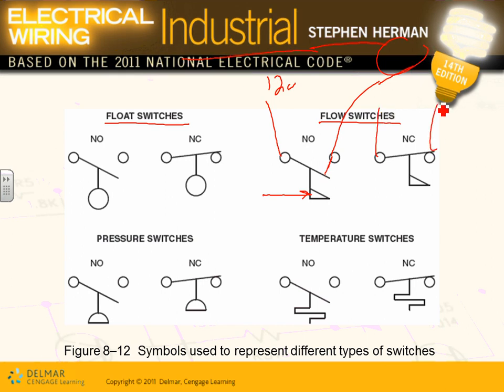So you bring all your wiring out of here. Here's my normally closed, normally open. I have a pressure switch driven by pressure. Temperature, these are all pilot devices. A temperature switch driven by temperature, a thermostat, normally open, normally closed. All these, Adam, are the interface into your control circuit. Any comments, gentlemen? Any questions?